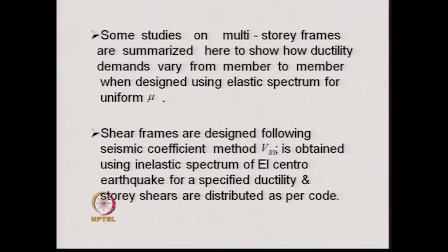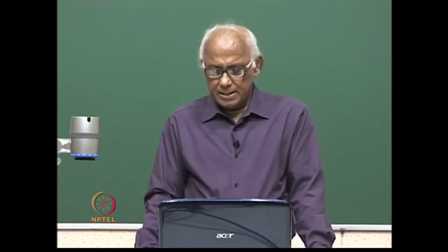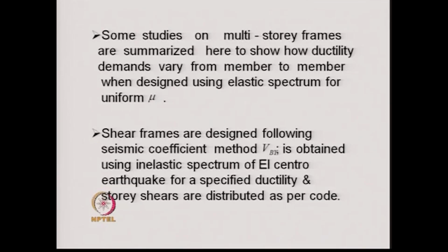So, that is depicted. Building frames of sizes 5 story, 10 story, 20 story and 40 stories were taken as case studies. The frames are deliberately kept as shear frames, so that only the columns are yielding.